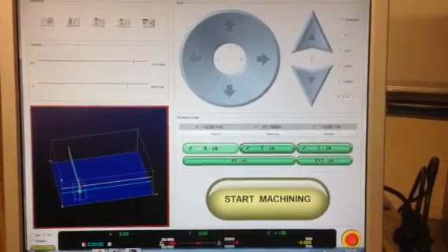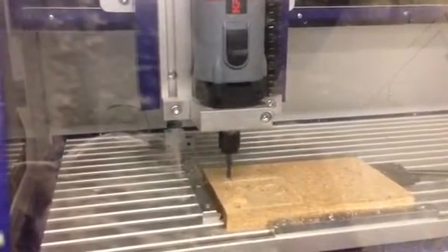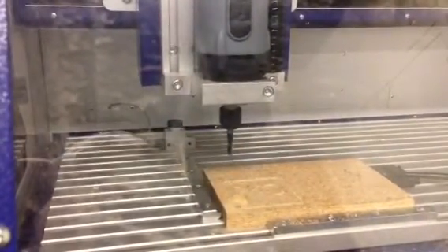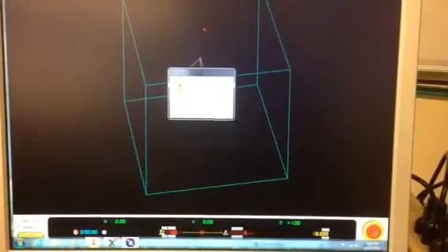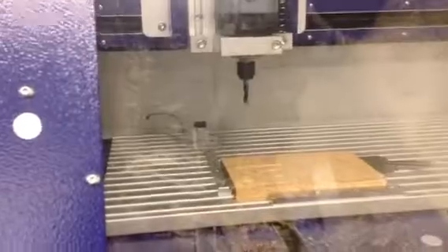Of course, when you're recording is when it's going to act up. All right, let's try that. Just down here. Okay, now okay. So once you hit OK and it knows it's in a safe location, I'll come up here and say okay, it's going to turn the spindle off, to cooling off step mode. It's just saying, is everything okay? Yep, everything's fine. Say okay. It's going to home itself. Everything's still okay. Just being extra safe here. Click OK. It's going to reference itself and then run the program.